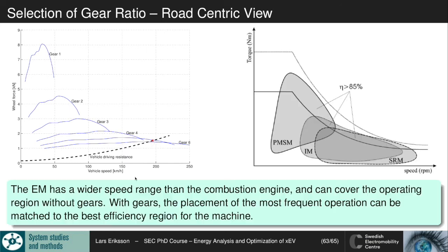If we look at the outline shape here, we have a wide range of torque and a wide range of speed that is managed by having a gearbox. But with an electric machine that has this kind of behavior, we could match the necessary driving like here. We would have high launch torque with only one gear, and we would have high speed from the high dynamic behavior of the electric machine.